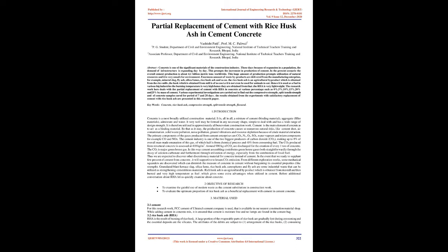The research work here deals with the partial replacement of cement with RHA in concrete at various percentages such as 0%, 5%, 10%, 15%, 20%, and 25% by mass of cement. Various experimental investigations are carried out to find out the compressive strength, split tensile strength and flexural strength of concrete samples cured for periods of 7 and 28 days. The results obtained from the experiments with satisfactory replacement of cement with rice husk ash are presented in this research paper. Keywords: concrete, rice husk ash, compressive strength, split tensile strength, flexural strength.